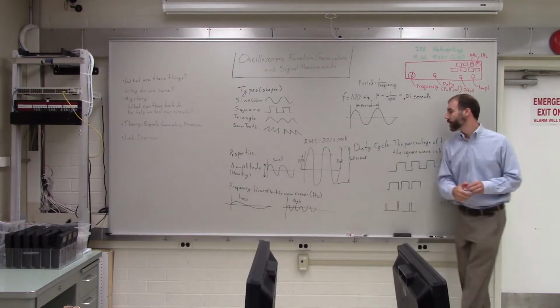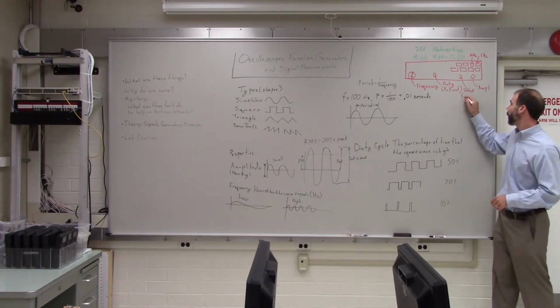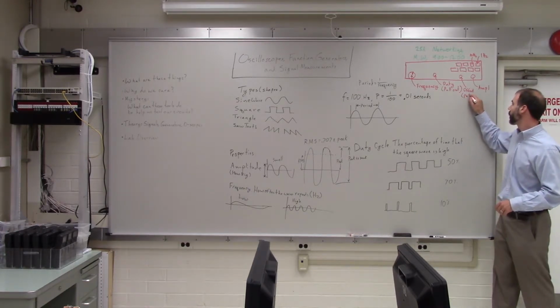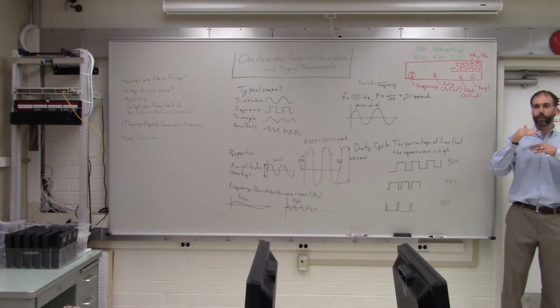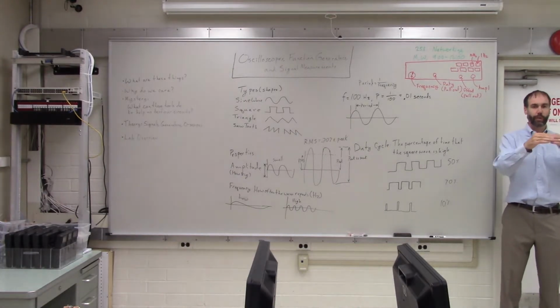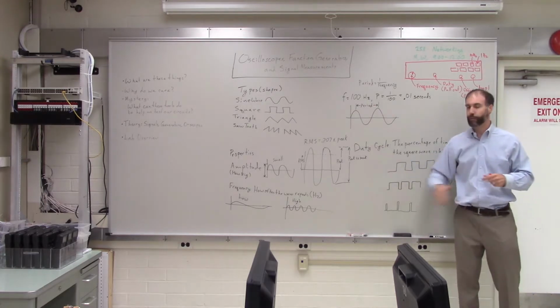Again, you have to pull the knob out in order for it to work. Normally, it's pressed in and it has no effect. The wave is just centered around 0, but when you pull it out, then you can actually use it to move the wave up or down.